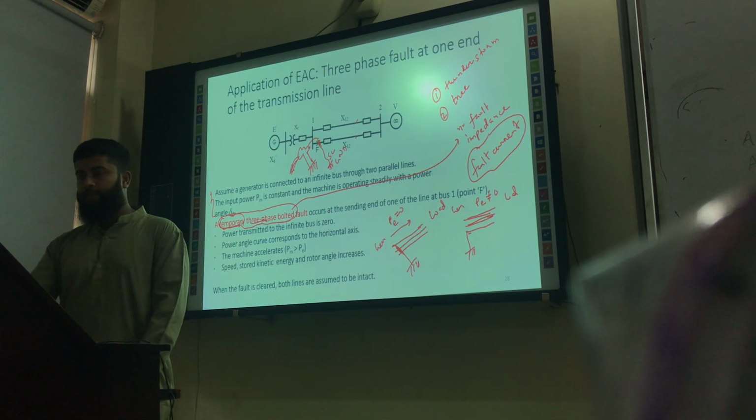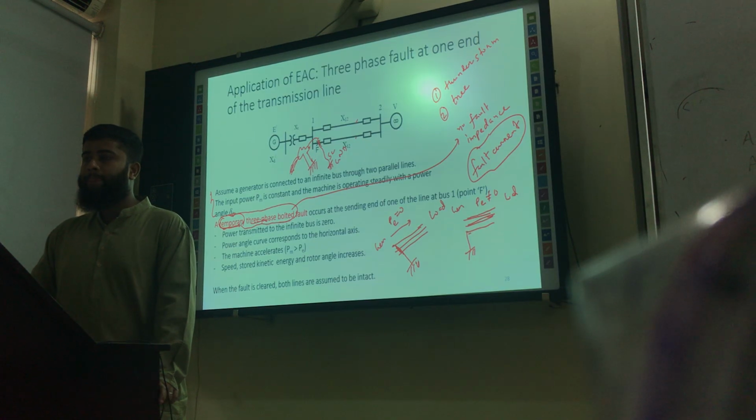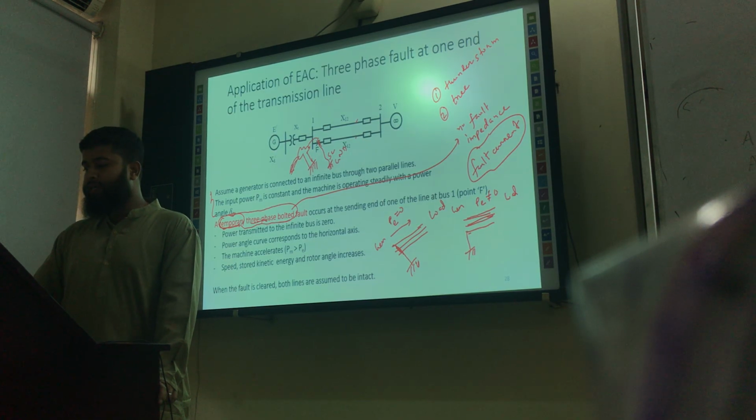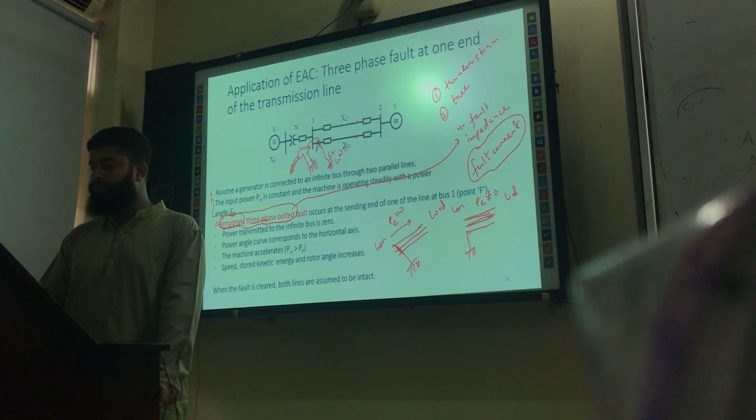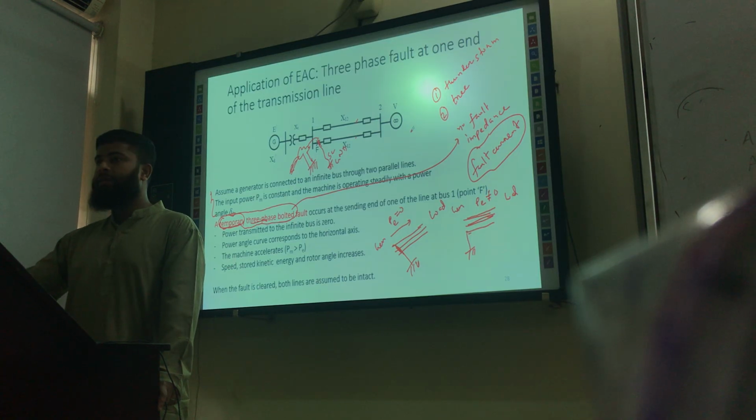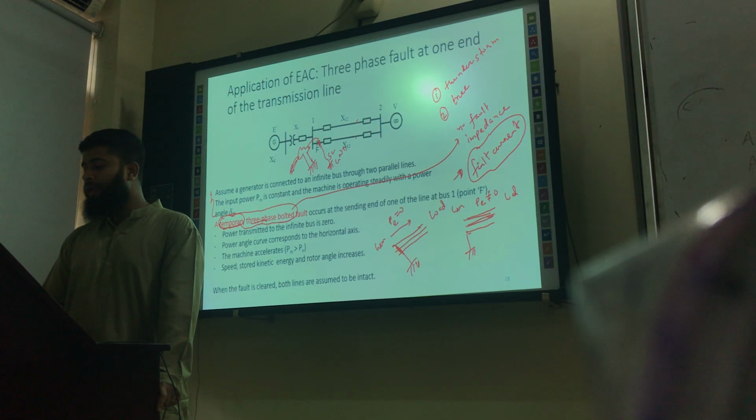Okay. So for this temporary fault, will the circuit breaker operate? Actually, the circuit breaker operation is a bit different. There are different types of circuit breaker, right? You will see some relay that can operate in terms of time. It will see how much time the fault is there. So if the fault clears before that time, the circuit breaker will not operate. But if there is another circuit breaker, let's say that is only responsible for the current flow, and it sees any current that is beyond that limit, that circuit breaker can be tripped.